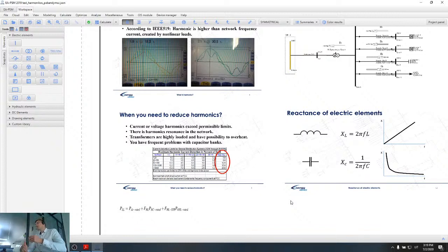Harmonics, because they have bigger frequencies, create eddy currents in the electrical network, and of course this can also saturate current transformers, and due to saturation, current transformers will give bad readings of data. For example, this can cause protection devices to trip without any fault in the network, only due to a high level of harmonics. So the main problem is overheating of the equipment, which shortens the lifetime of the equipment, so we have to change equipment more frequently because of the overheating.